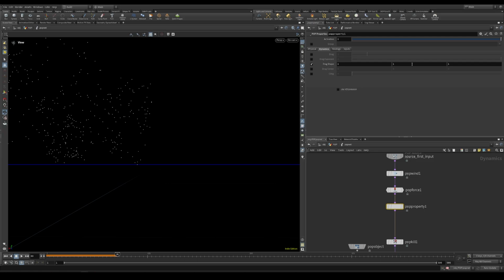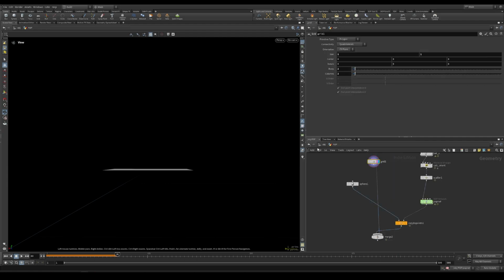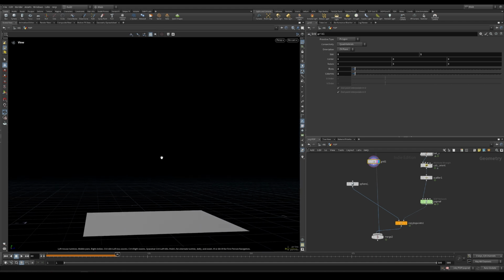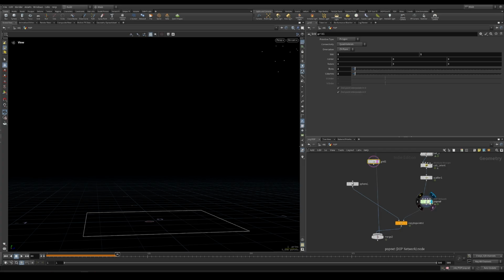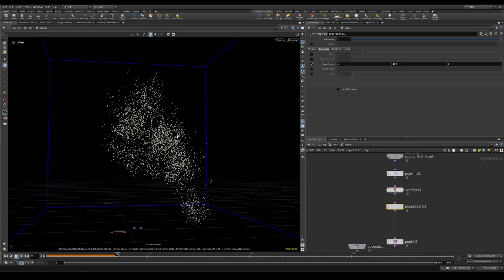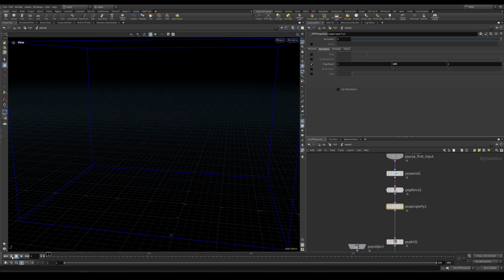And what we want to do is actually to have the drag shape 1 on the x and z axis of the grid, but we want to set it to something like 100 on the y axis. This will say basically on the y axis of the point, you will apply 100 times the drag coefficient. So we should really see some difference now in the simulation.